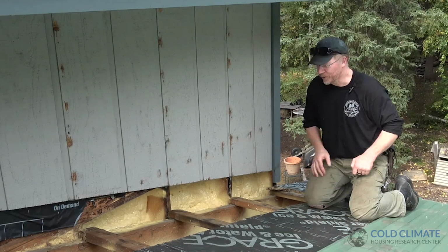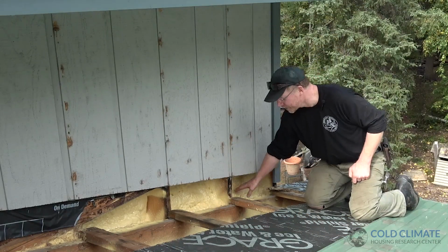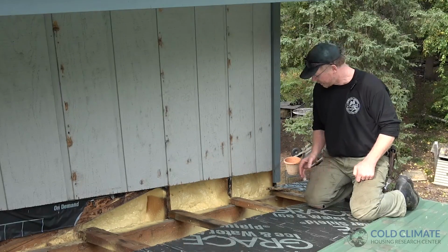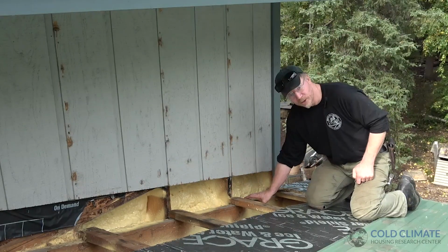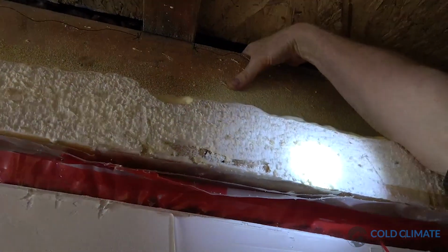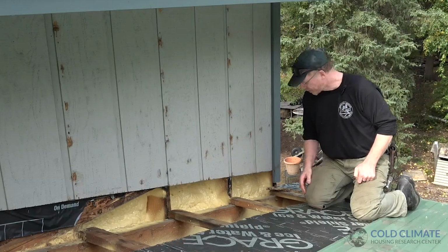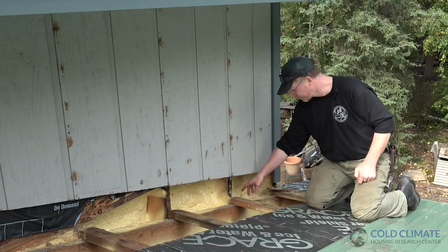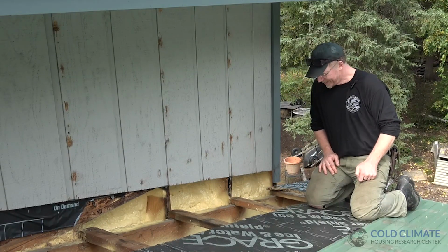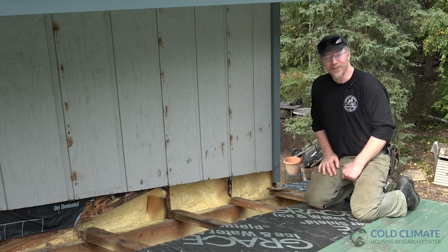The smoke test will tell us if we continue to have air leakage in any of these bays, which we suspect. Remember, I was able to reach over this bay in the wintertime and grab wet fiberglass. We've taken the fiberglass that was in here out, but that was a strong indicator that there's still an air leak bringing water vapor from inside into this bay. So our next step is to conduct that smoke test and see what we can learn.